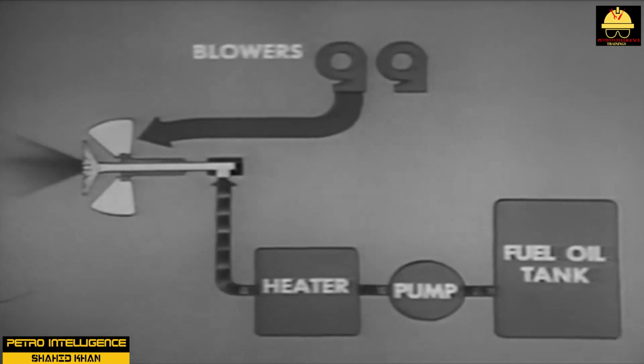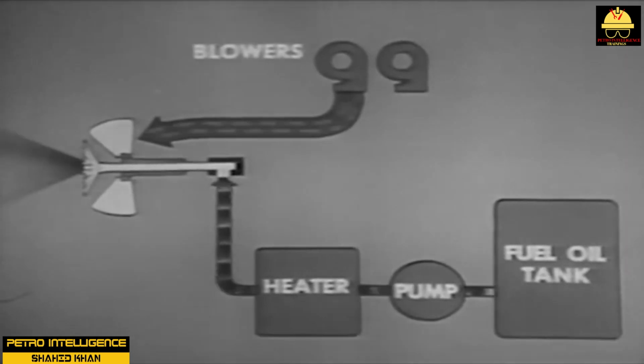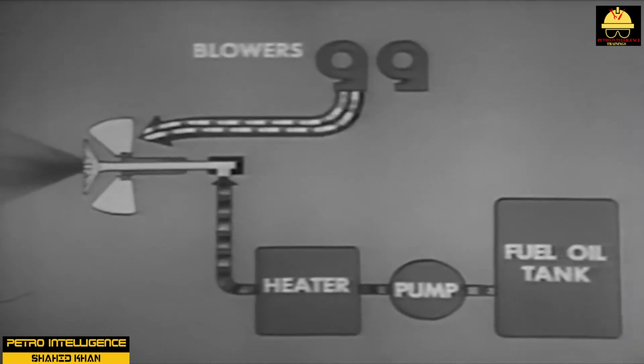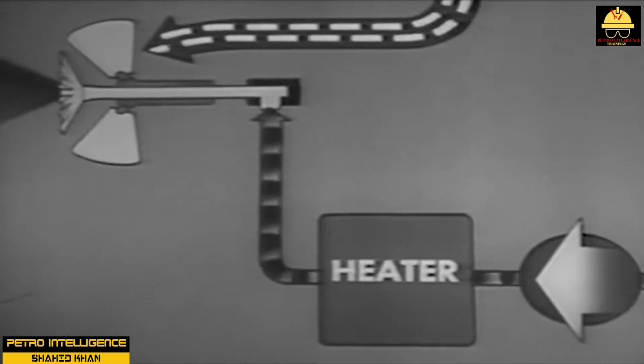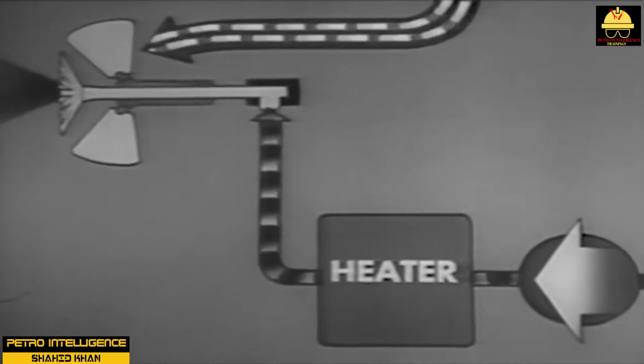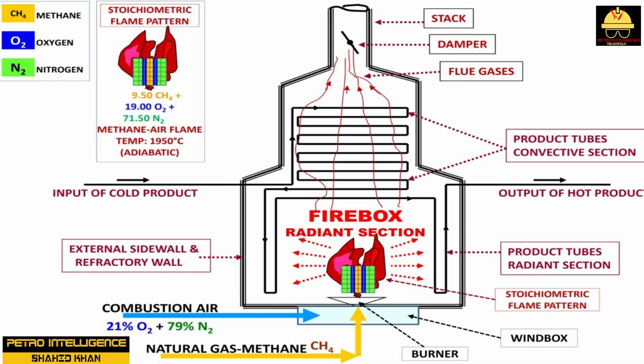The burners are designed to avoid direct contact of the flames with the tubes in the firebox. A space of 1.5 to 2 feet is considered to be a safe distance between the open flames and the radiant tubes. The burner's flame pattern should be less than 60% the height of the firebox. The radiant section is engineered to distribute the radiant heat energy evenly.